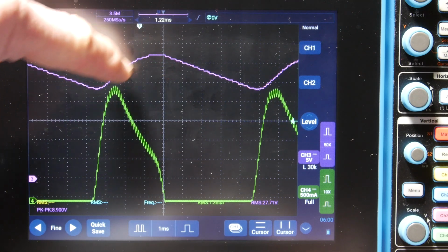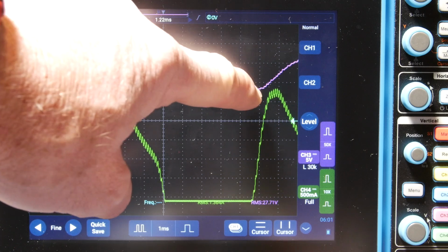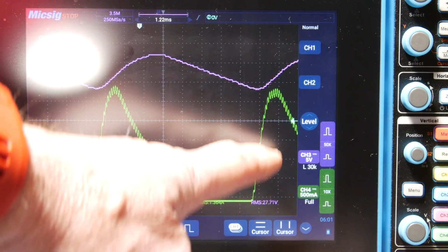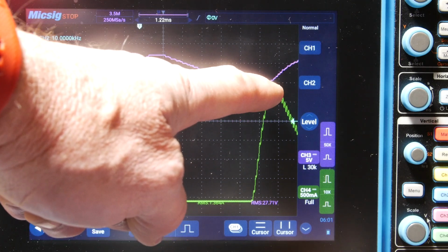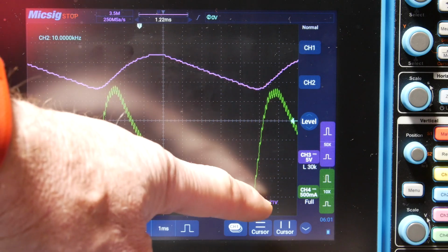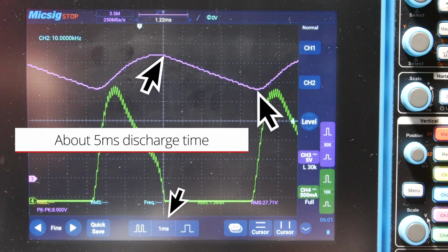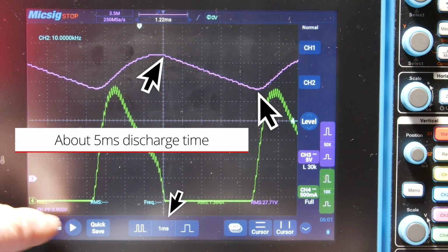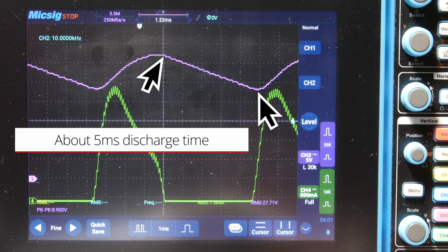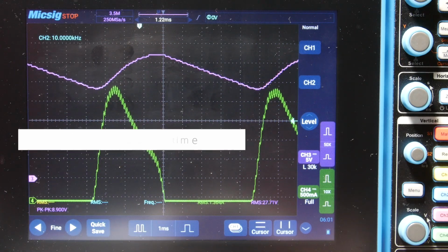You can see where it sags down is the end of this cycle, and right where it hits the low point, the input voltage is coming up, which we're not really looking at. Maybe I should have looked at that. But you can see where the current turns on. Right there is where that voltage sags. And again, now look, 8.9 volts peak to peak. So a little bit less voltage because we don't have that lower frequency pulling at it.